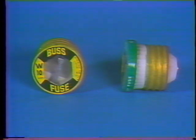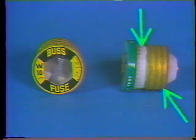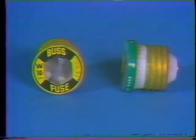A plug fuse is constructed so that it can be screwed into a fuse socket. The fuse element is enclosed in an insulated housing that's usually made of porcelain or glass. You can see the fuse element through the window, made of glass or mica. And since you can see the element, you can tell by looking whether or not the fuse has blown.